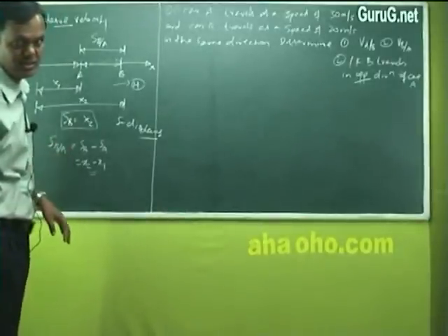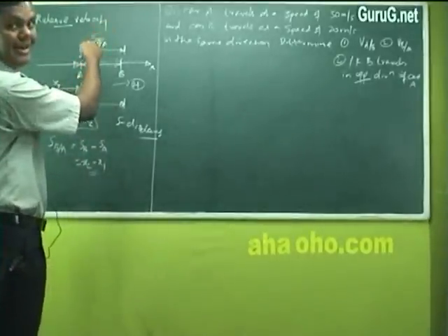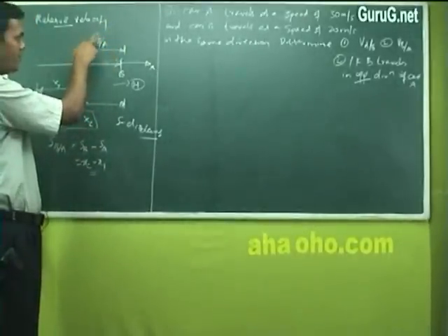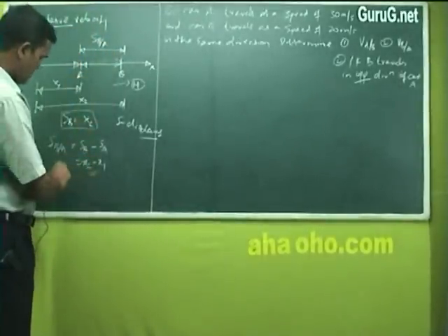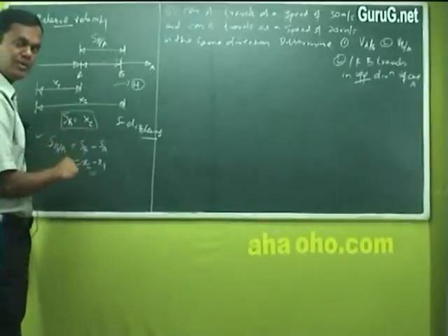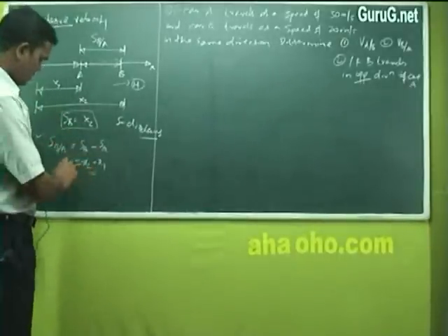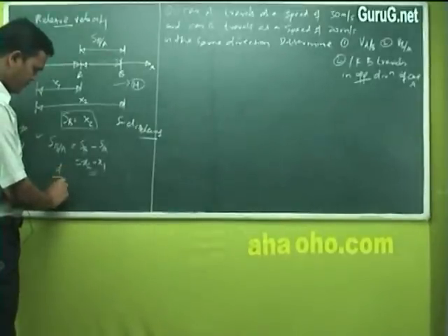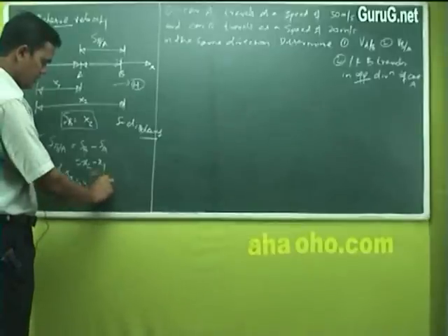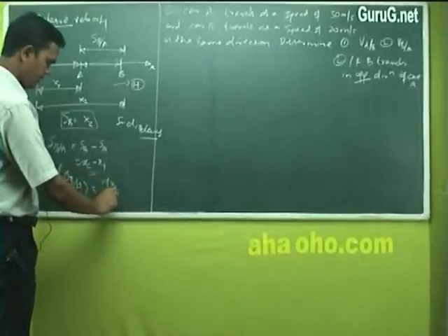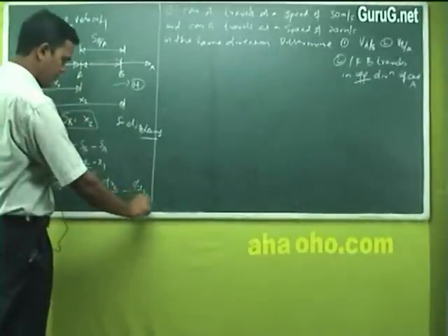Now if you want to know the velocity, what do you have to do? Kindly remember, this symbol denotes the relative displacement of body B related to A. Suppose I write A to B, vice versa, same thing. So this is the displacement now. If you want velocity, what will you do? Once you differentiate displacement once, you will get the velocity. Now d by dt of your displacement, what will you get here? dx2 by dt, is that not? Minus dx1 by dt.